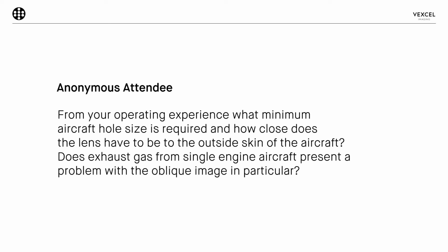From operation experience, what minimum aircraft hole size is required, and how close does the lens have to be to the outside skin of the aircraft? Does exhaust gas from single-engine aircraft present a problem with the oblique imagery in particular? In my understanding, a 19-inch hole would work with the UltraCam 4.1, but this is a very specific question on aircraft installation. How close the lens needs to be to the outer skin depends so much on the design of the airplane, where the wheels are and so on, that there's no general answer to that.